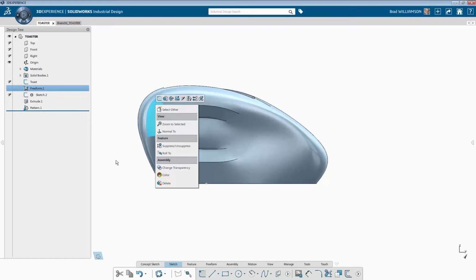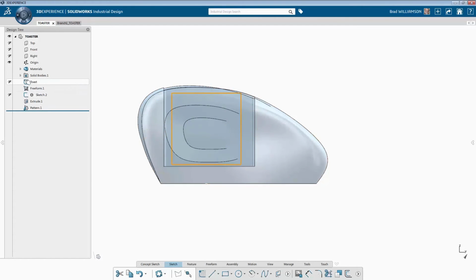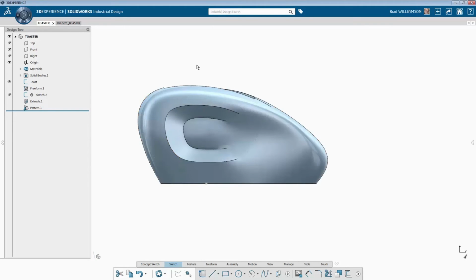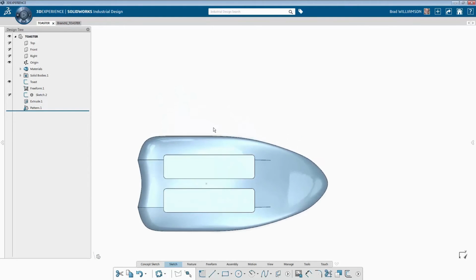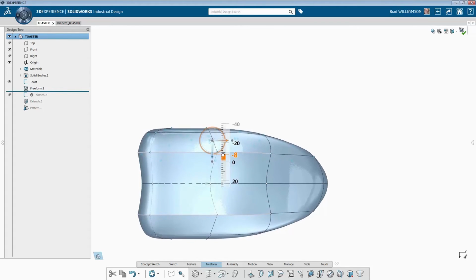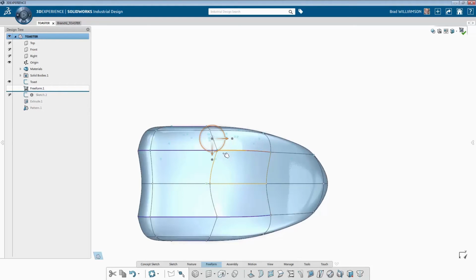In the front view, everything looks good. Enabling transparency here, I can see through to a photo of a piece of bread. That lets me know the slot is properly located. However, in the top view, I can see the whole shape needs to get wider so the slots don't cut through that nice styled ridge along the top of the tank. It's easy just to widen the toaster body by dragging the handles, and immediately I see the slots will fit much better now.